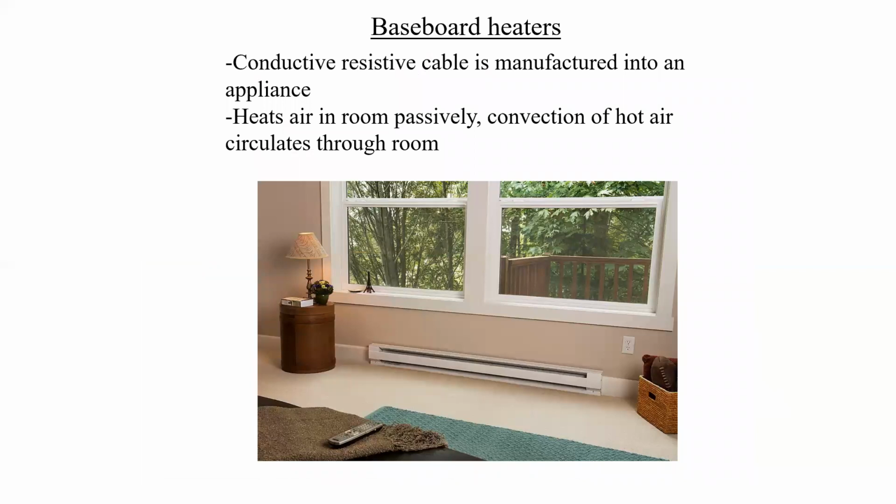Baseboard heaters, probably the most common of all types of heating apparatus. A conductive resistive cable is manufactured into an appliance, and as that wire heats, the air passively moves across the heating fins, and it heats the air in the room through convection.